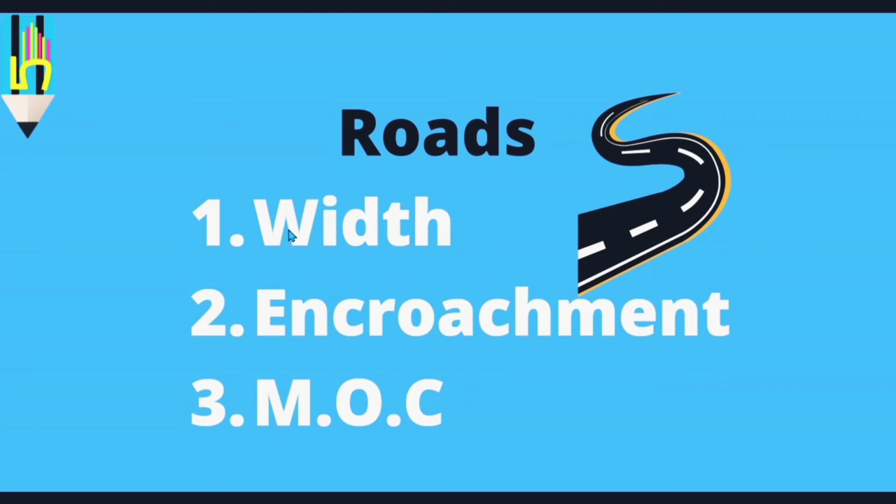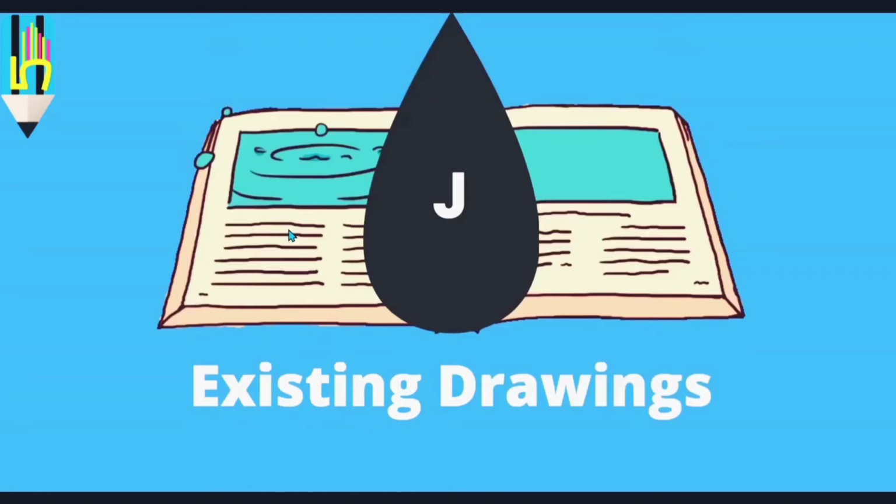So you have to build the road with the same quality of material that it was built with already. For example, in hilly areas they prefer concrete roads, RCC roads, but in plain areas we mostly prefer bitumen roads. While estimating the cost of the total project, we include the cost of road replacement. So if we know the type of roads and the length of those roads, we can have a better estimate of how much cost it is going to incur.